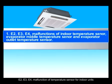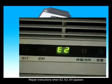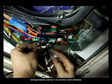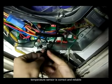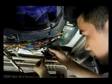E2, E3, E4, malfunction of temperature sensor for indoor units. Repair instructions when E2, E3, E4 appears. Step 1. Check if the cable connection of indoor temperature sensor is correct and reliable. If the connector is normal, please go to next step.